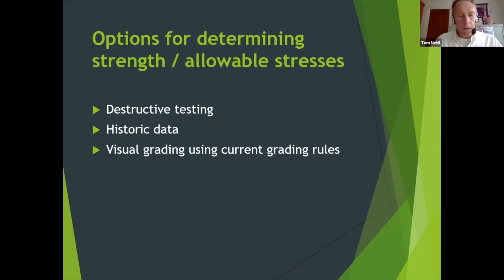You need many, many samples, first of all, to get even a statistically meaningful representation, because no two are going to be the same. But you're missing the point, which is that the strength of the stick is largely governed by the defects that are in the entire timber, not by the strength of the wood where it's all nice and clean.